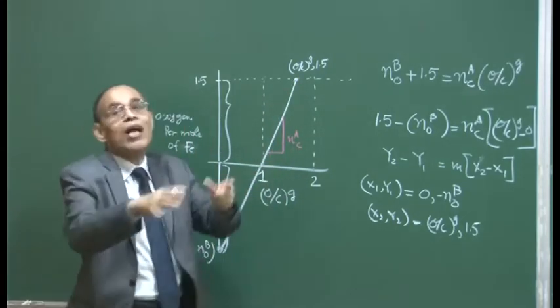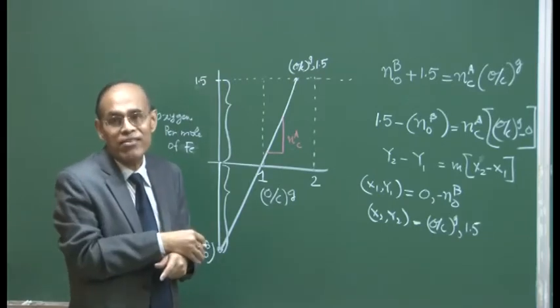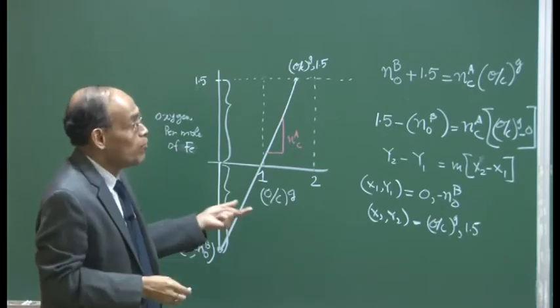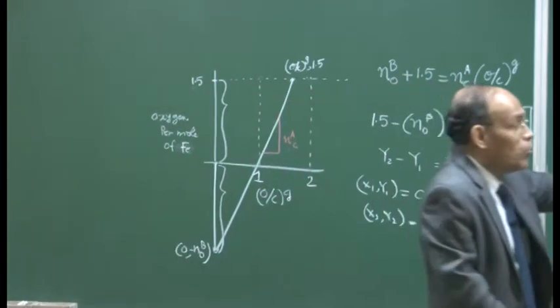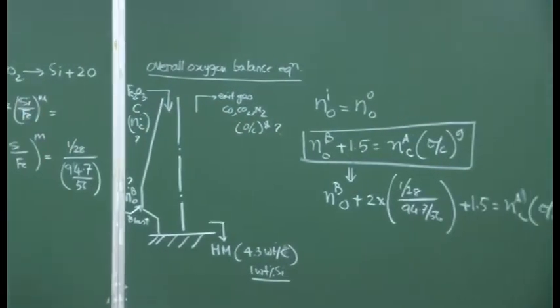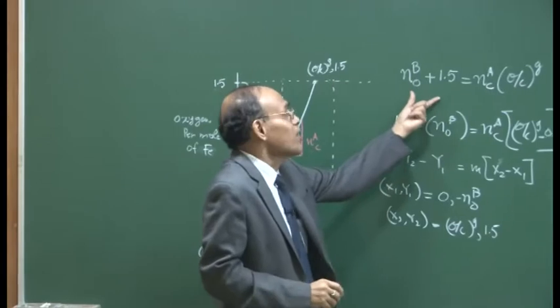That means all the carbon monoxide ascending from the tuyere region has actually taken part in the reduction reactions, and in turn has oxidized into CO2 and manifested in the exit gas, with a large volume of CO2 relative to the volume of CO. So, it is understood that this equation is not fully predictive, because there are 3 variables.